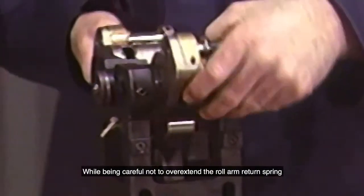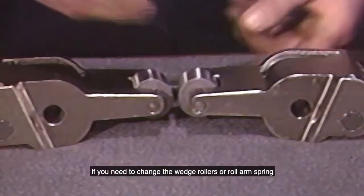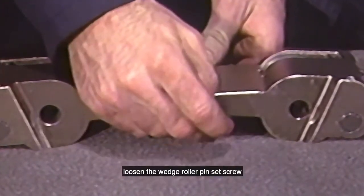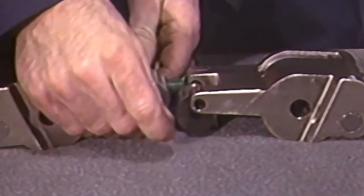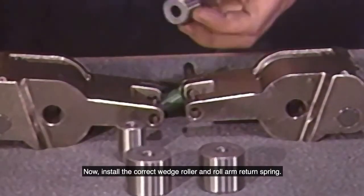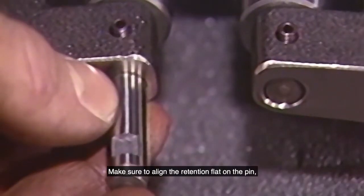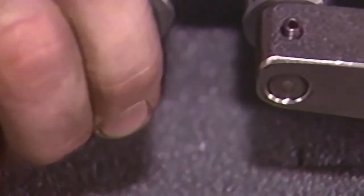While being careful not to overextend the roll arm return spring, remove the roll arm assemblies from the attachment. If you need to change the wedge rollers or roll arm spring, loosen the wedge roller pin set screw and remove the wedge roller pin, the wedge roller, and the roll arm return spring. Now, install the correct wedge roller and roll arm return spring. Make sure to align the retention flat on the pin, insert the pin, and tighten the set screw.